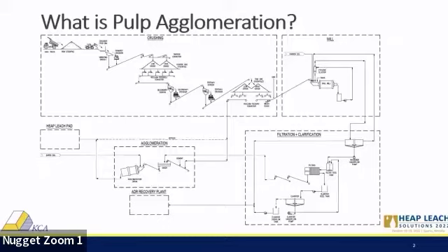The filtrate and the thickener overflow contain leached metal values, which were then sent directly to the ADR recovery plant. The filtered cake was combined with low-grade ore and agglomerated using an agglomeration drum. That was then stacked onto a leach pad and leached for further recovery.